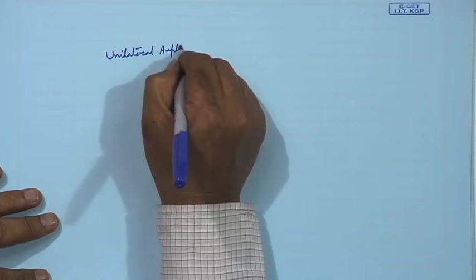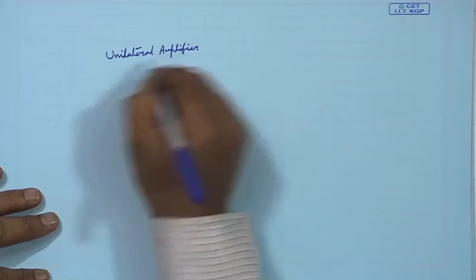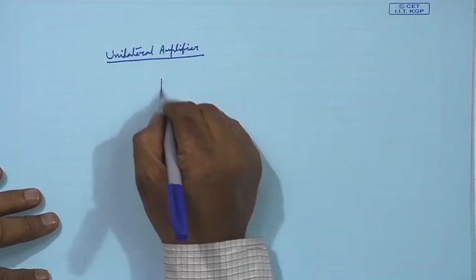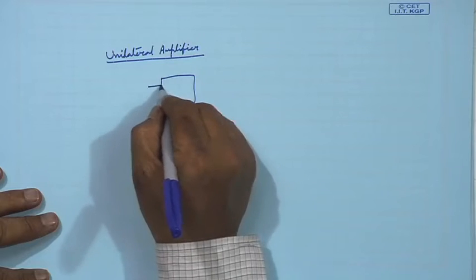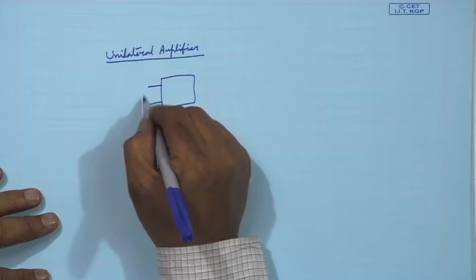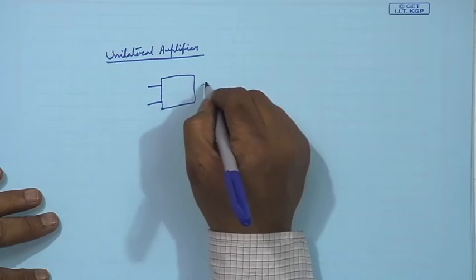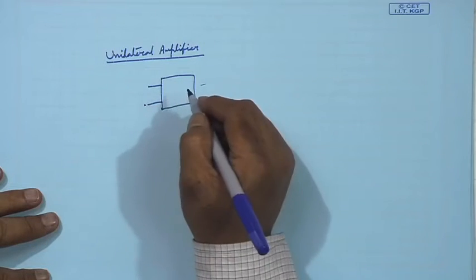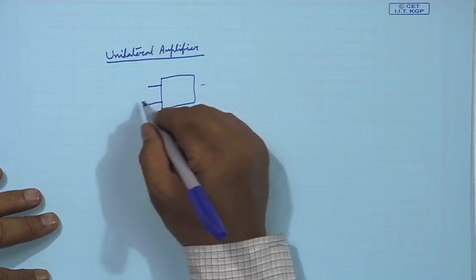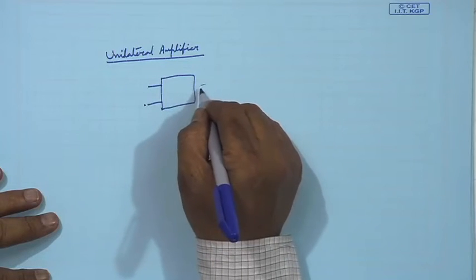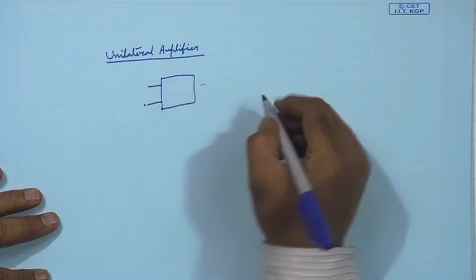What is the meaning of S21 in an amplifier? Please remember that in a two port network, S21 means whatever I am giving here, how much is coming here. So this by this is the S21. What is S12? If something is reflected, how much is coming here.